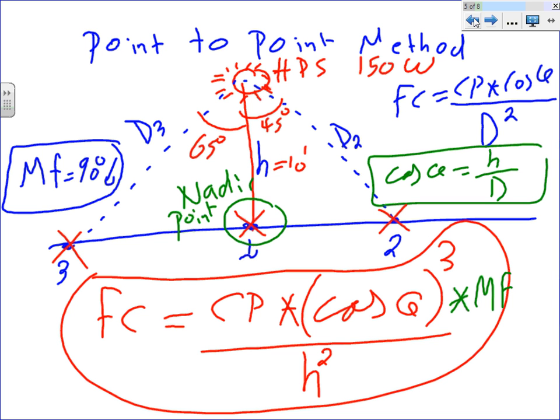If you're outside or inside and you need to guard that fixture from physical damage, and you put that little basket over it, what do you think that's going to do to the light? Shield some of the light. So they add another factor that's called guard factor. All you're doing is adding derating factors.